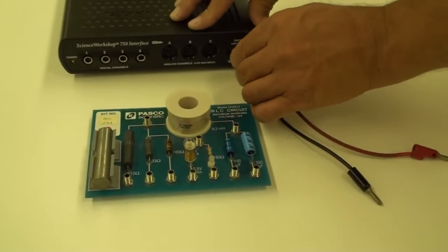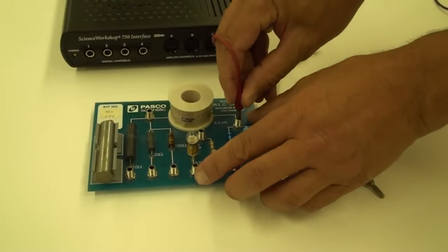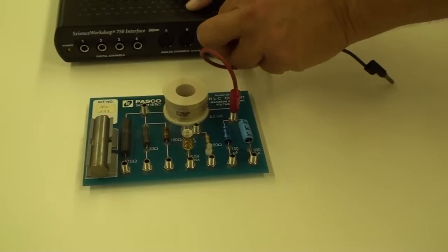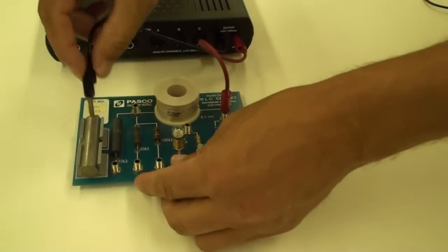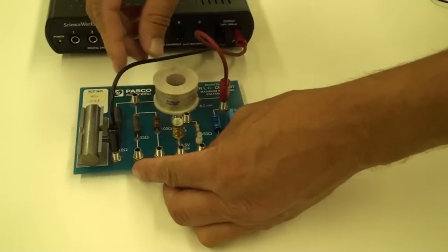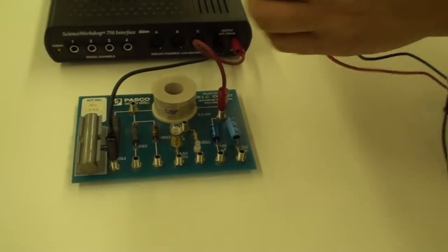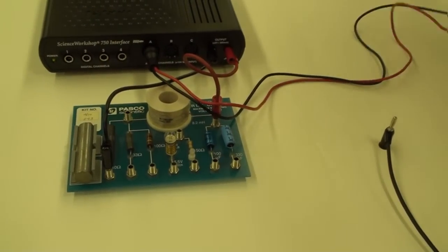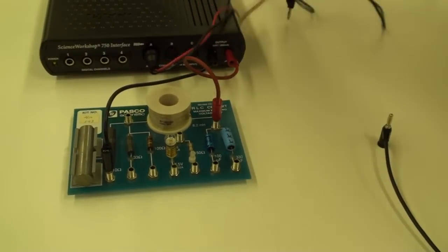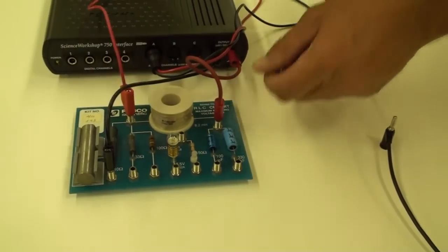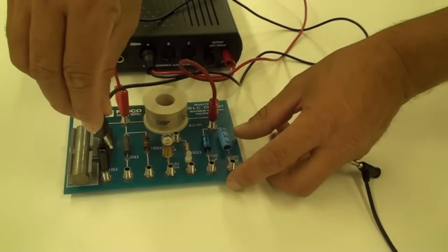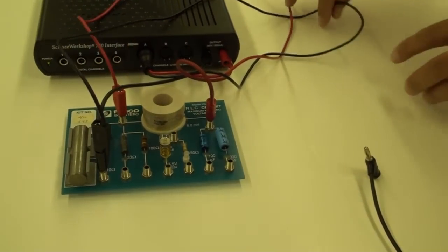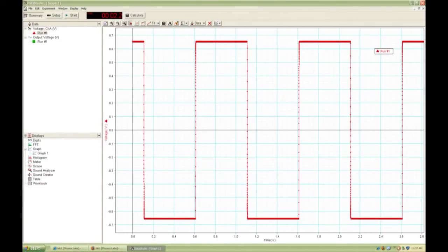Because the time constant for this small coil is short, you cannot keep up with a mechanical switch. Use the internal power supply set for square wave mode to flip the circuit on and off. Though we cannot measure the current directly, we can monitor the voltage across the resistor and know by Ohm's law that the current will be proportional. The current in the circuit appears as a square wave, toggling on and off.